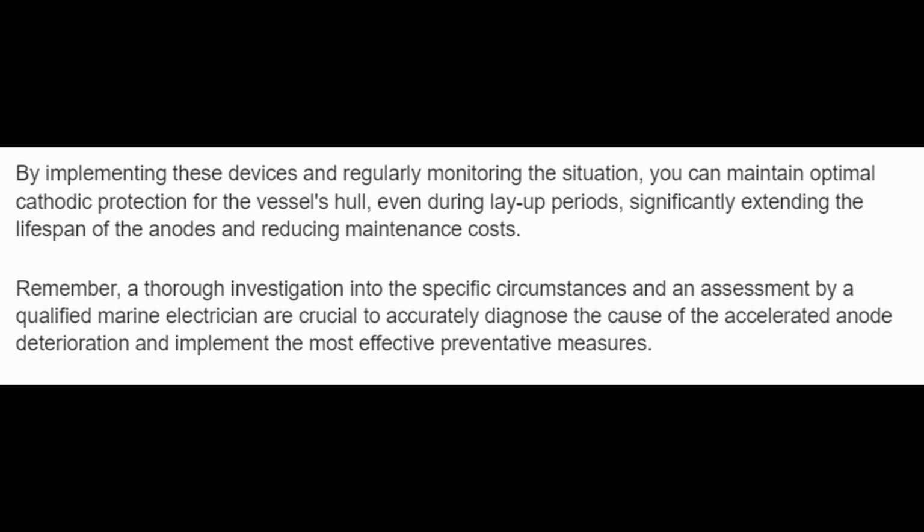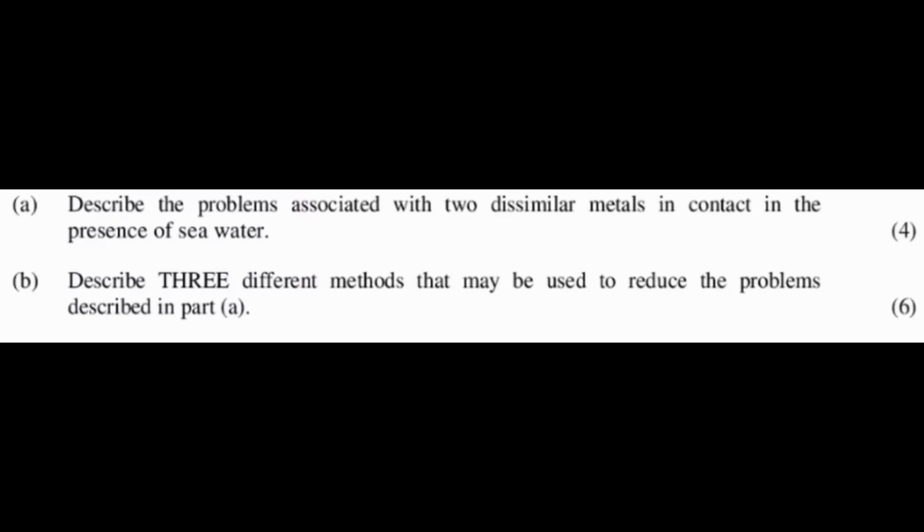Remember, a thorough investigation into the specific circumstances and an assessment by a qualified marine electrician are crucial to accurately diagnose the cause of the accelerated anode deterioration and implement the most effective preventative measures. A. Describe the problems associated with two dissimilar metals in contact in the presence of seawater. B. Describe three different methods that may be used to reduce the problems described in A.